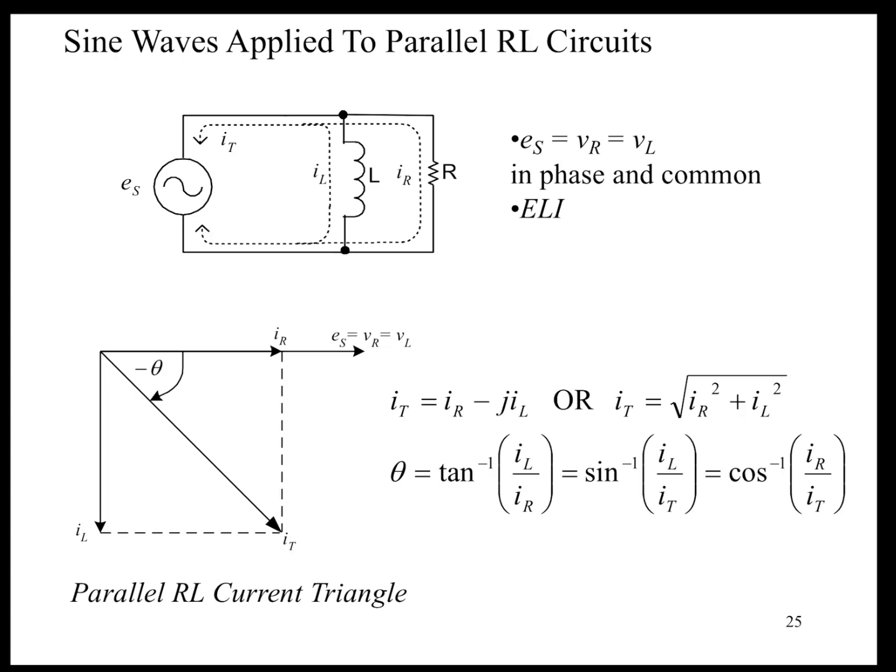So that means in this case, how would you determine Z total? Well, Z total just has to be determined by R multiplied by XL over R plus jXL to give us a product over sum value. This would be product over sum, and this would give us our Z total value. You have to understand that because it's parallel connections, you can't just add them together like you could when they're in series.